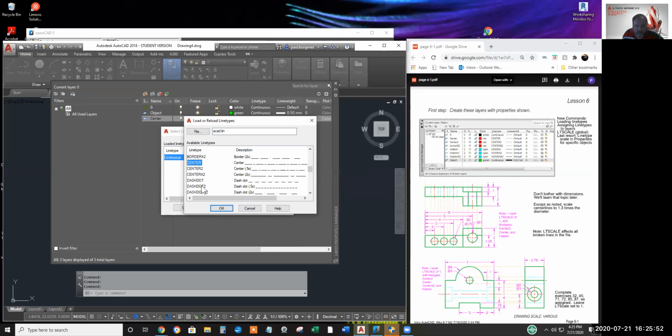Click the top one, hold shift, click the bottom one to select all of them from top to bottom with the shift key. And while I'm in here, much as I like repetition for training's sake, I'm going to include these 3. I'm using the control button.